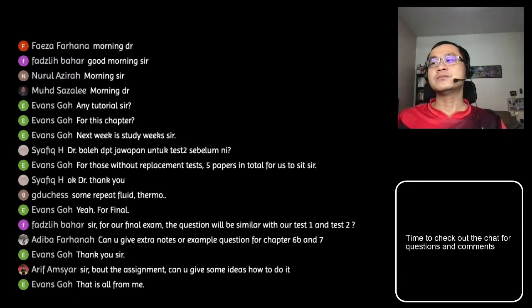So based on these two criteria, when you frame up your problem which is not defined very clearly, you have to tell what your target steady state error is, whether you want to reduce it to zero for a ramp input or whatever it is, and at the same time what performance you want to achieve.